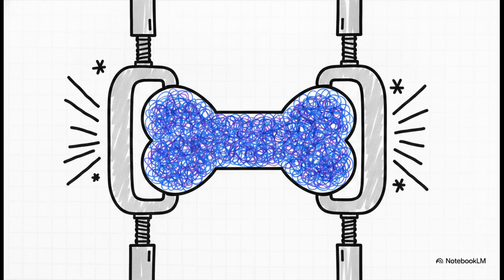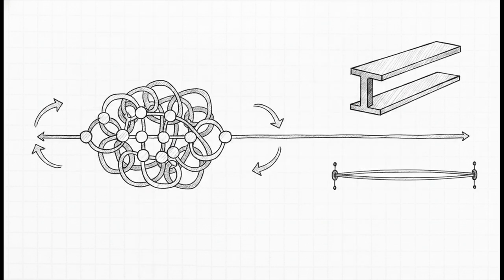This equation, sigma equals F over A, defines exactly that, and it is highly dependent on those molecular chain entanglements. If you've got high molecular weight and high crystallinity, your cross-sectional area can withstand a massive amount of applied force before it fails. But wait, what if you want the part to bend without breaking?